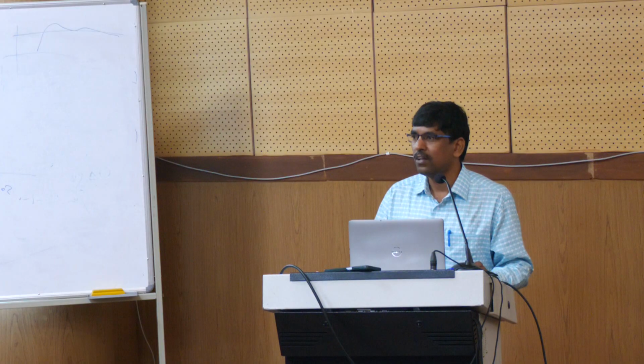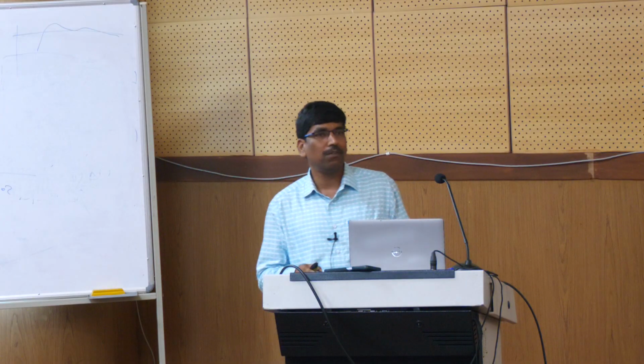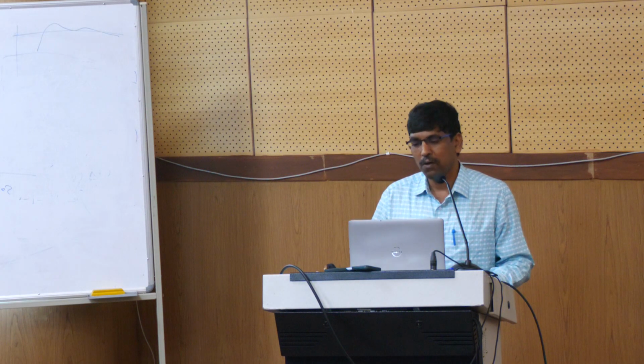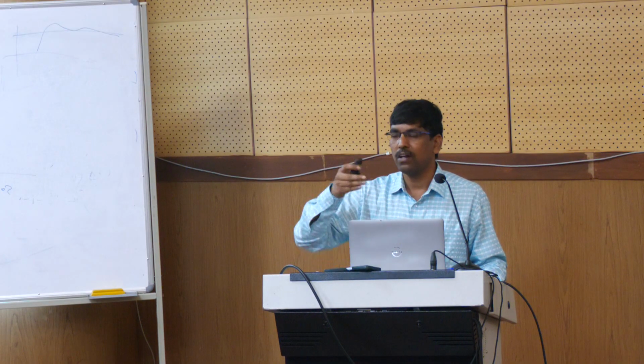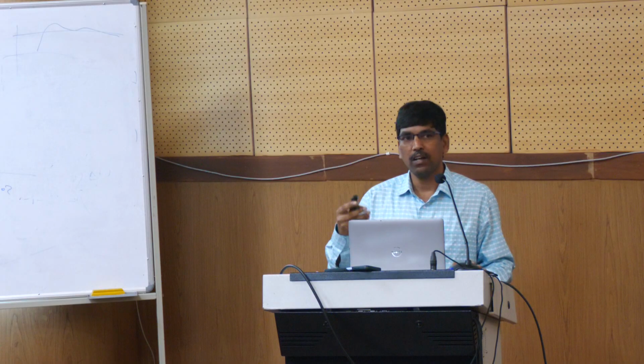The V by F ratio is maintained constant, so the voltage and the frequency are maintained accordingly to get different speed conditions. Now, the question is how you are going to improve the THD. One answer is increasing the number of steps. What will happen by increasing the number of steps?